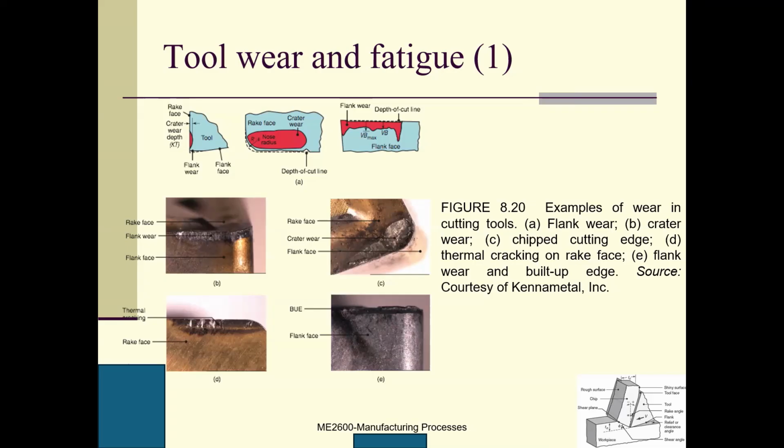Question. It's like the built-up edge having a little bit of the material weld to the tool, or something? How does it happen? Because of the compatibility of the tool material and the workpiece material at some temperature, they attach very, very closely together. So it depends on the compatibility of these two materials.